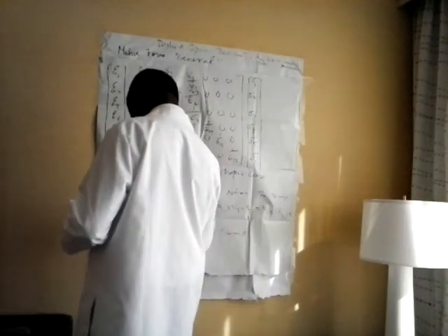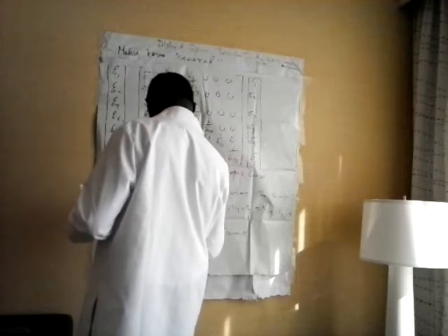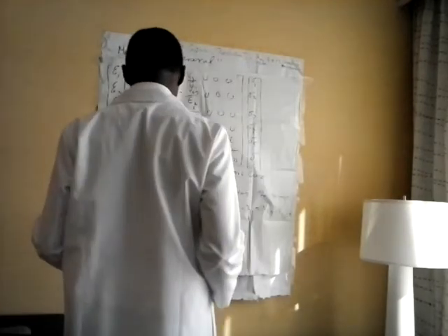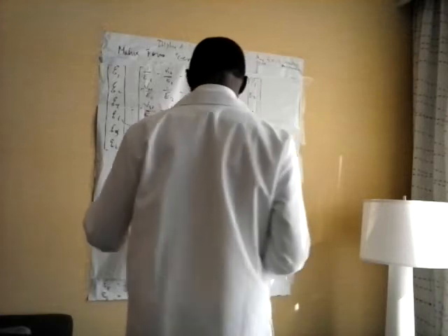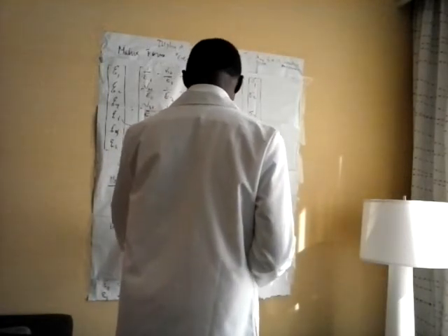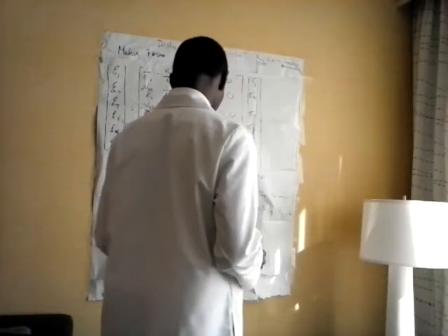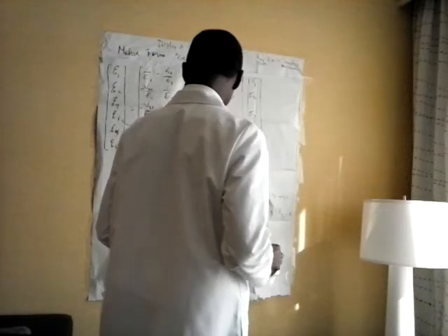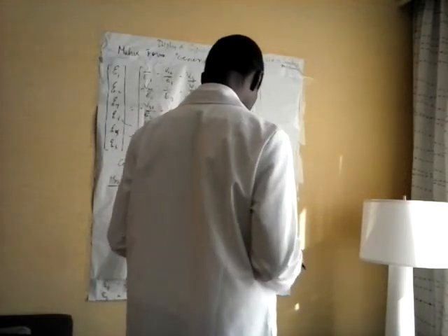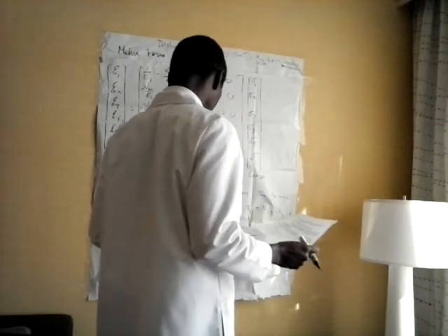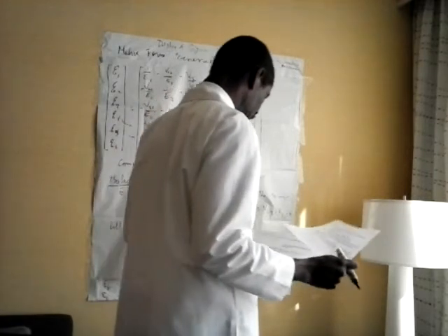And we have now that G4 equals G5 equals G6 equals G. And this is for the isotropic case, in which the extensional moduli are the same, the Poisson ratios are the same, and the shear moduli G4, G5, G6 equal G are the same. So let us see now the matrix form of the isotropic case, the orthotropic case, and the anisotropic case.